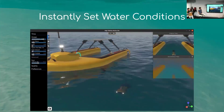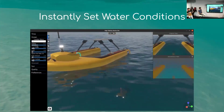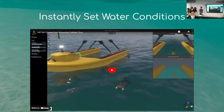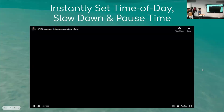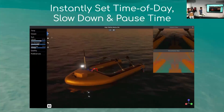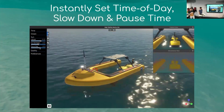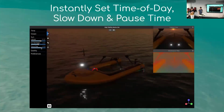While it could get similar profiles, where you give in this much force and you get out a velocity, and the curves were similar, you'd have perhaps an error of 20 to 30% in velocities. I think the reason for that is because we were simplifying the geometry quite a lot in order to run it in real time. That's one of the trade-offs we made. If you really want that high accuracy fluid dynamics, you have to go with a computational fluid dynamics method. So we were able to get within 20 to 30% of real.